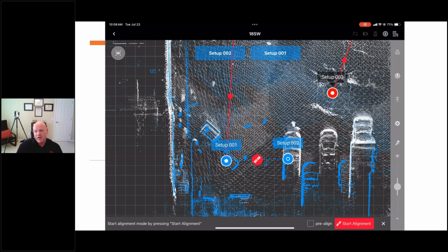answer. The big caveat is if you're going up and down stairs, like half flights, there's a lot of similar answers in stairwells. And also, if you're going farther away between your scans, you're going to need to do a better job of manually giving it a guess before you hit pre-align, because pre-align fits together 3D features, and it's sort of like quick align, but it's got quick align and optimize built in, kind of.